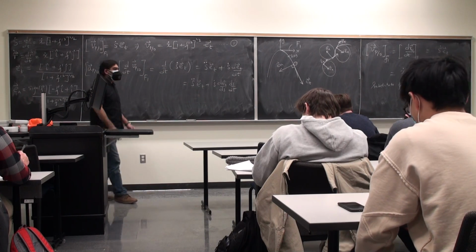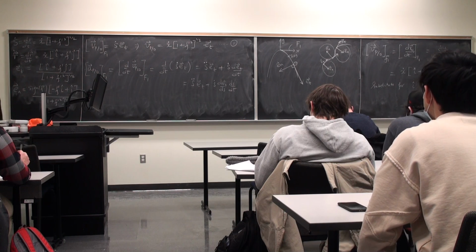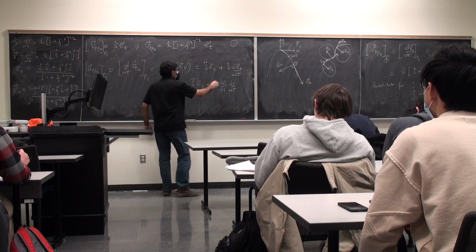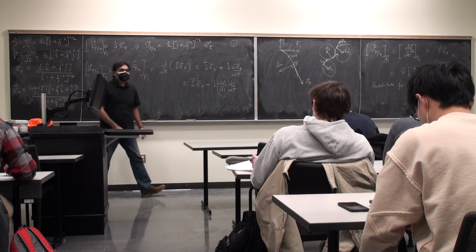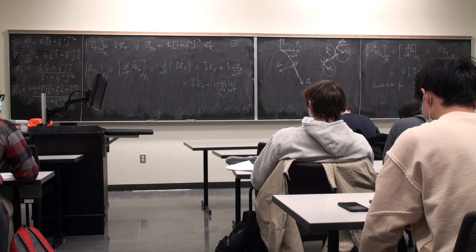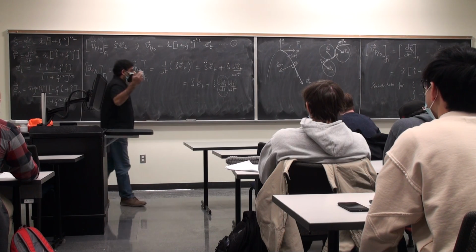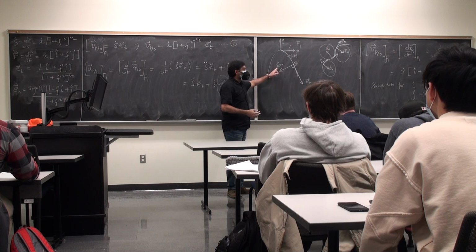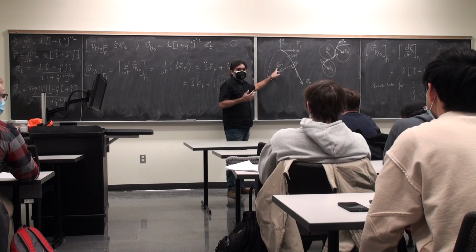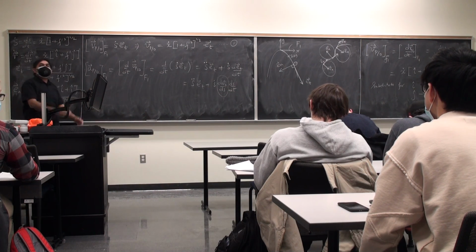By the end of the day, you'll get pretty tired of seeing it many times. But it's very important to see in the perspective of dynamics. ds by dt is s dot. What is this term here? Anybody? Yes, the line going towards the center of curvature. It is nothing but the normal direction. But you have to write it as kappa times en. You see from the definition of the first Frenet-Serret formula, we said that dEt by ds is kappa times en.